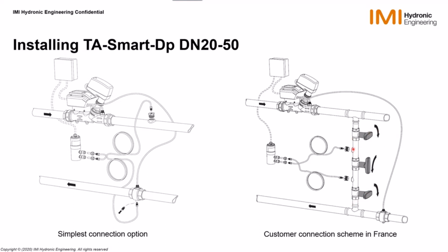You are opening here to get the same pressure, and you are doing your connection in a safer way by having bled off probably the things before. And once you are ready to go into operation, you can open one side, open the other side, and then finally you can close this valve to apply the delta P on the delta P sensor.